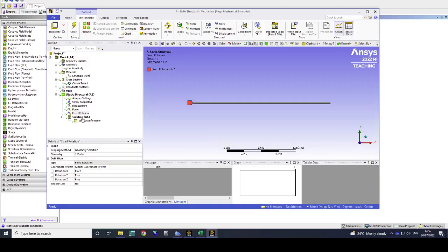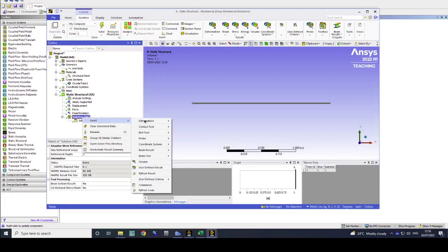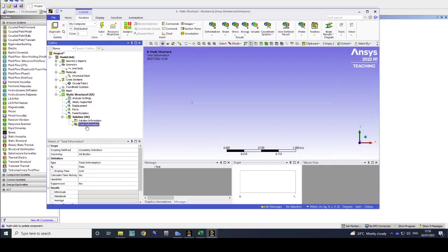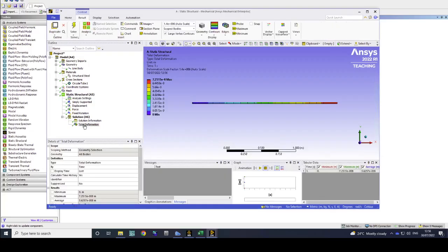There we go. So we've got the solution, no problems at all. And if I look at deformation, I need to evaluate this in the results. And this is the deformation, okay? So the animation would look like this. Essentially we are stretching this beam. Or if we had a negative force, we would be compressing this beam, but nothing that would look like a buckling mode. So essentially we need to do the eigenvalue problem solution now.